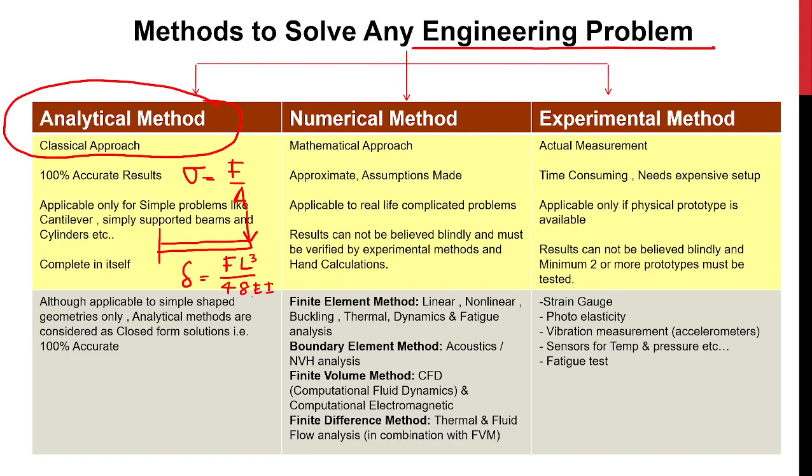This is the formula. How much force at the end? And then the length of the beam, cubed, over 48 EI. E stands for elastic modulus. I is the beam moment of inertia. And you can solve a lot of problems. Other problems like summation of forces is equal to MA. These are analytical methods that you learn in class. A lot of courses teach analytical methods.